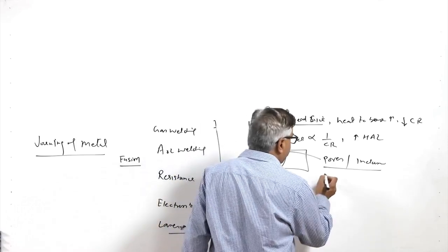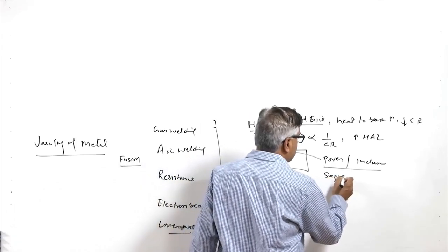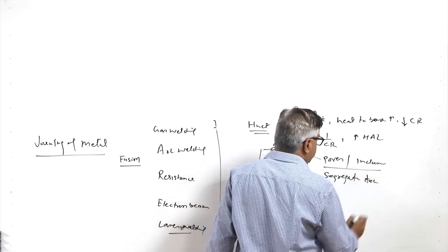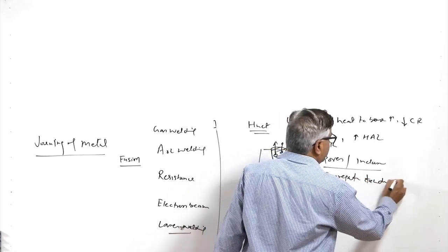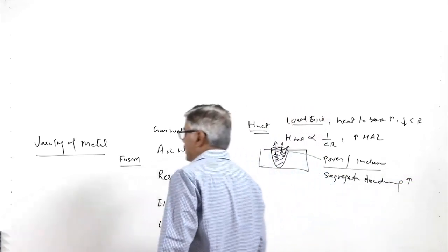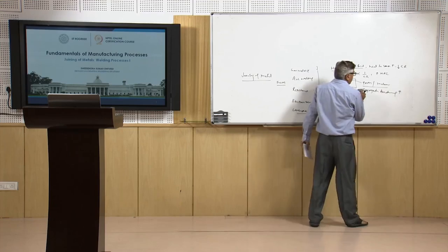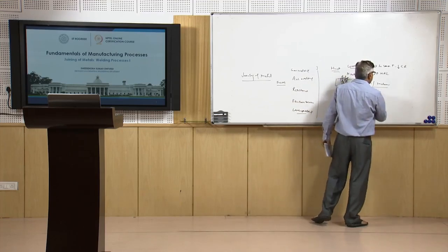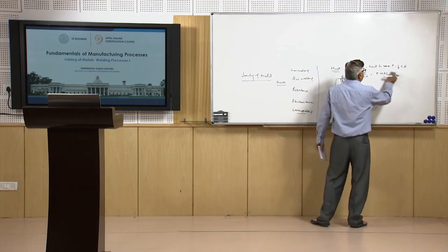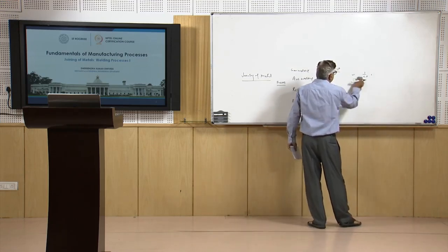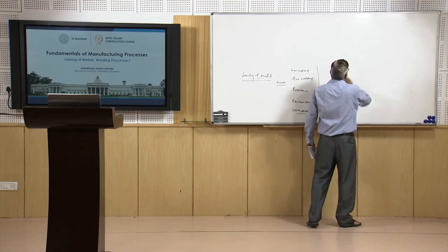At the same time, segregation tendency, especially in case of the alloying elements, increases with the increase of solidification time and reduction in the cooling rate. So, these are some of the effects which are related with the heat input.